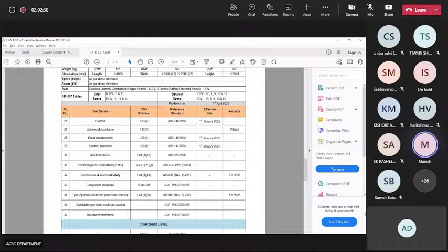Stand requirement is there from January 2022. There is some 10 lakh cycle application of the side stand that has to be done. Those tests are part of the homologation that need to be done. External projection is like if any vehicle has any crash guard or any kind of projection, that is checked there.